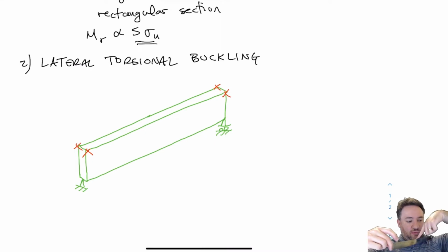You see, when I push down on this, I'm resting it on my shoulder and on my hand over here. When I push down in the center, it's very hard to get this section to fail. What happens instead is I push on it and it wants to just twist and go off to the side. And that is very common in deep sections. Now, of course, that is not possible if I bend it like this. When I just push in the center, it's always going to go straight down. And this way I can easily get a moment failure from section moment capacity in the center.